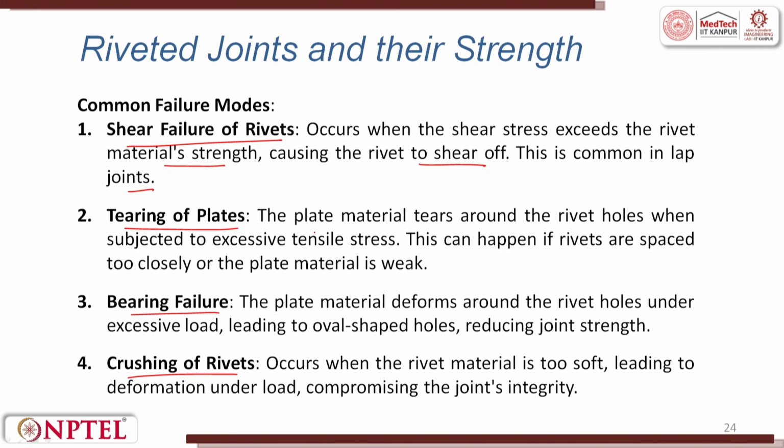Tearing of plates: the plate material tears around the rivet holes when subject to excessive tensile stress. This can happen if rivets are spaced too closely or the plate material is weak. This is kind of a fracture strength.